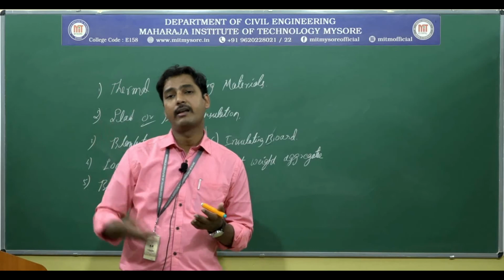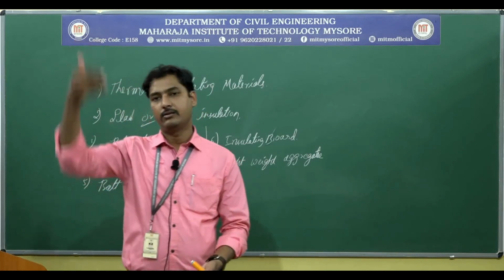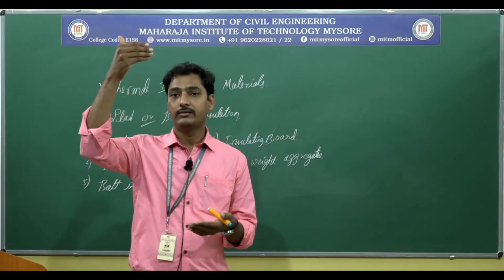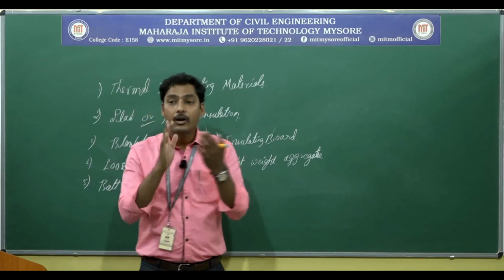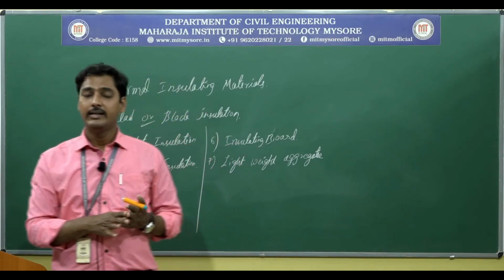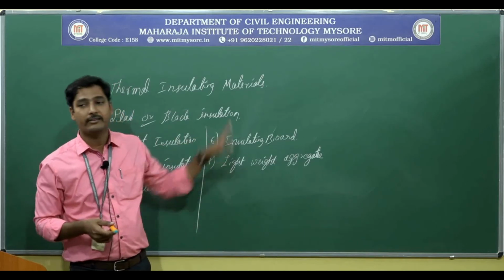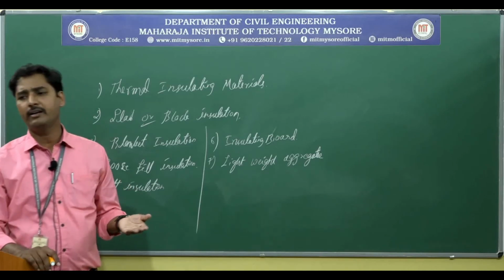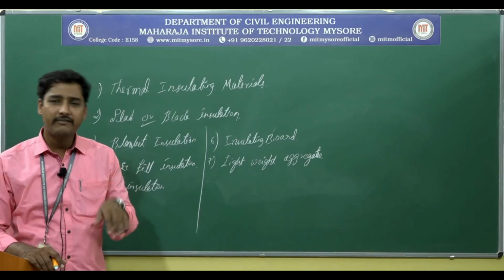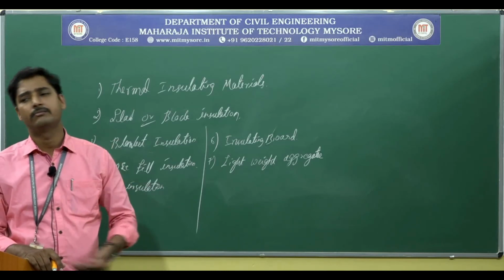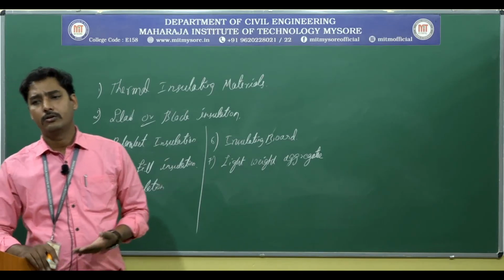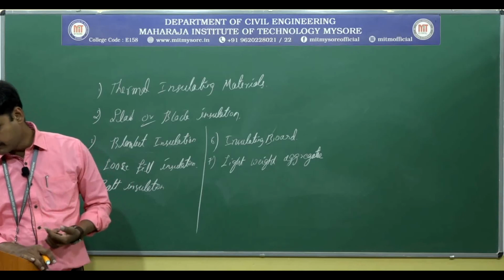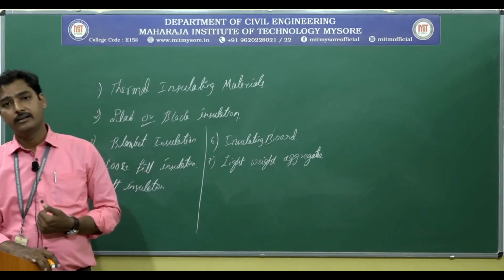G plus 10, G plus 12, yes or no. As the building rises vertically, the uppermost parts of the building need to be light in weight by adopting the lightweight concept. Even at the time of preparing aggregate for concreting, we can use lightweight aggregate. It might be naturally available lightweight aggregate, that is pumice, or we can use artificial lightweight aggregates, by adding some mineral admixtures together with cementitious materials. That is also one of the very good insulating techniques.